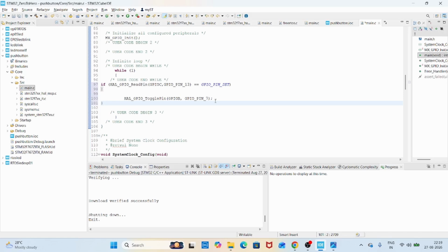Okay, but here one more thing we have to add. Let us say the user presses the switch and keeps it in pressed condition. Then we have to consider each press separately, right? Because if the user presses one time without a delay, it will be considered as multiple presses. That is called key debounce, right? And for that we have to add a small delay over here.